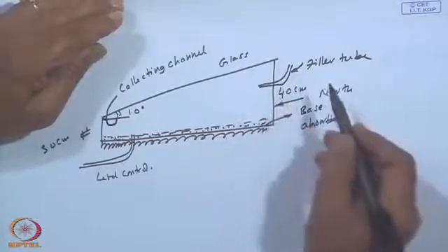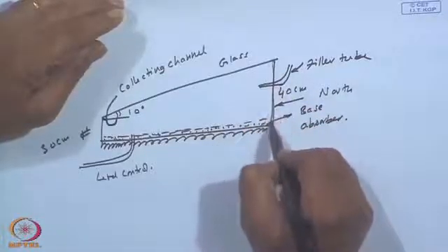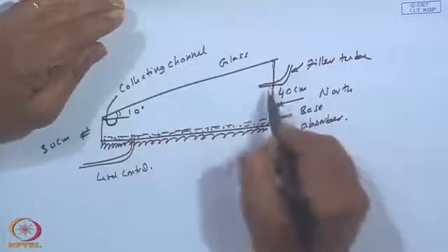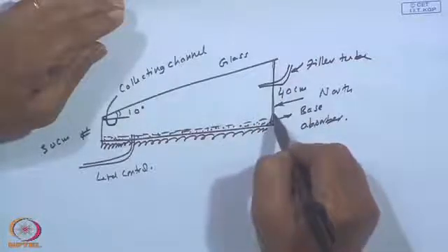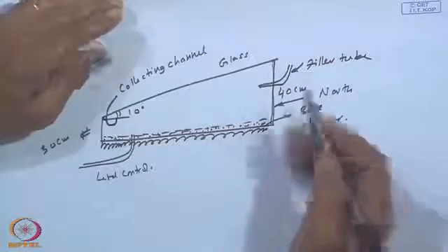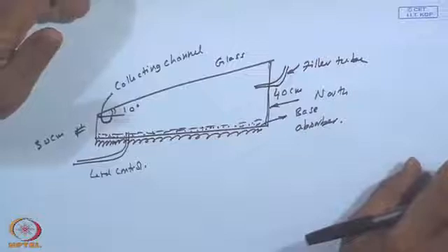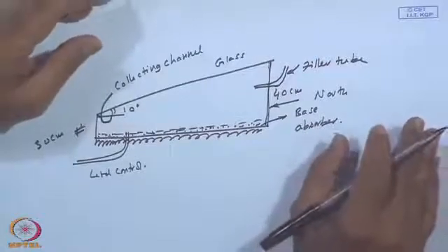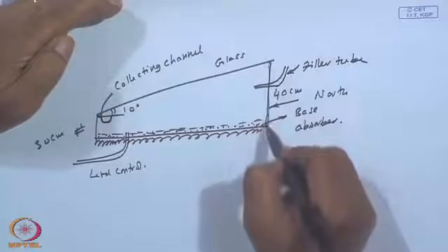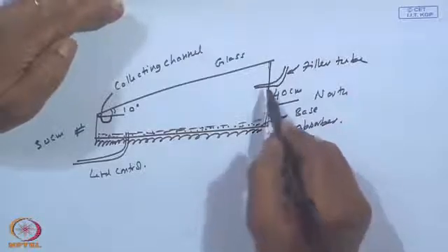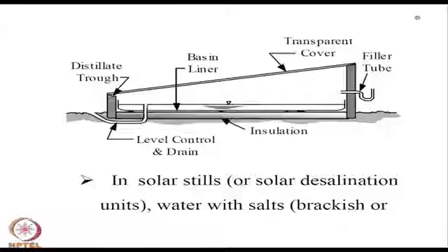Others will say that will also cause a loss, so instead make it black and non-transparent, and that will absorb radiation, and the absorbed radiation will in general heat the surface and heat the water. Whatever the argument, probably there was no discernible difference in performance whether you put a transparent glass on the northern side or a black painted opaque surface.